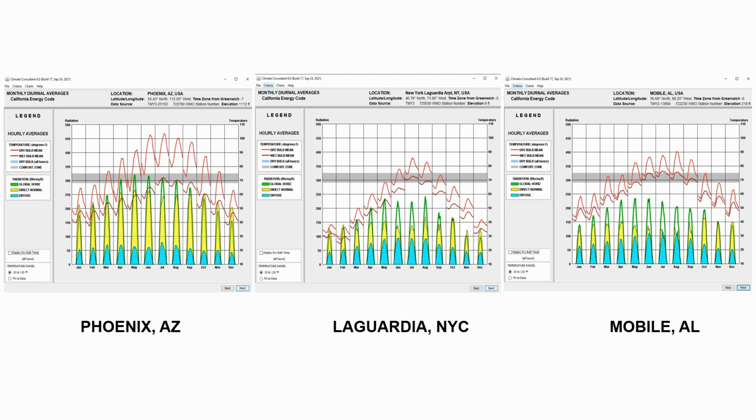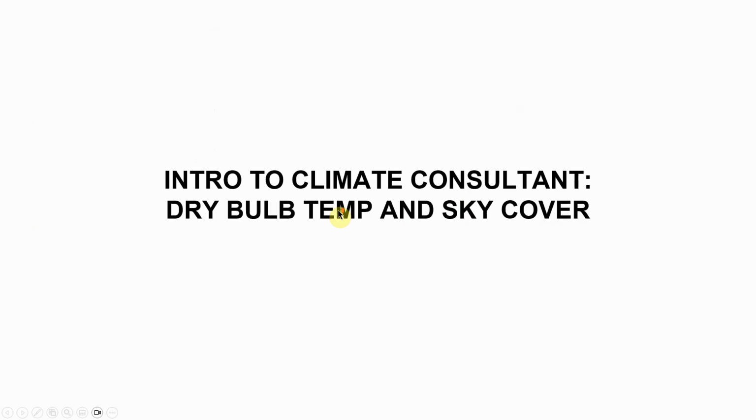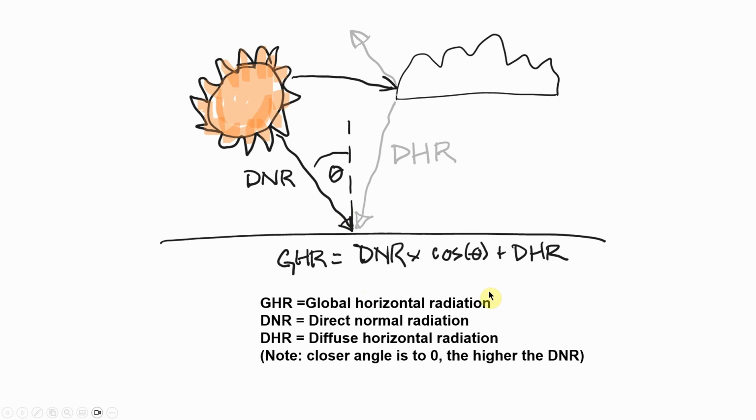We'll just stay here. So remember, actually, let me go back to earlier in this. Here we go. This is good. Remember that we were saying that we have several variables in terms of the sun coming in and hitting our surface, whatever we're talking about. The most basic metric is called direct normal, and that's saying wherever the sun is pointing, whatever angle it is in the sky, we have a surface that is pointing directly at it. So in other words, the rays of the sun are normal to that surface. It's perpendicular to that surface, and that tells us the amount of energy that's actually coming in.